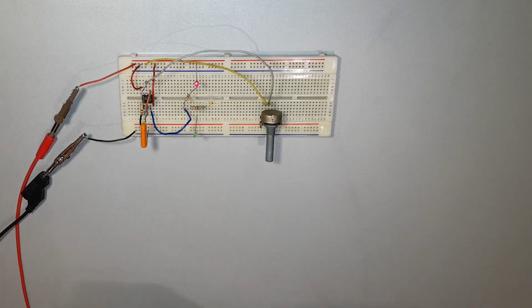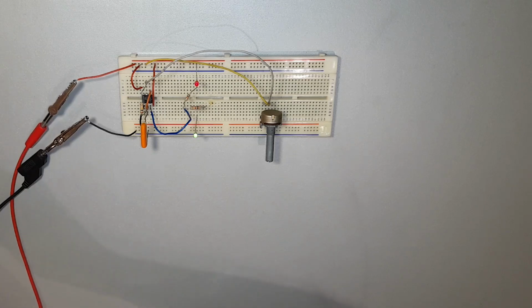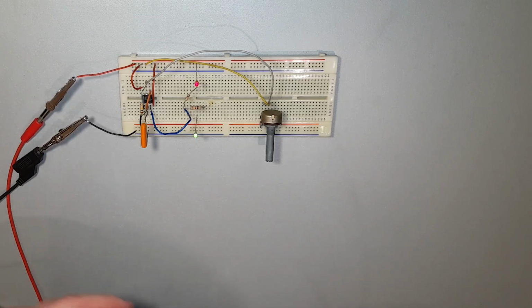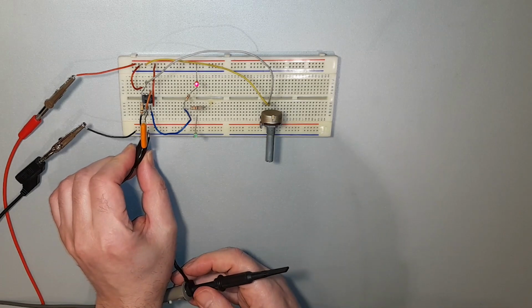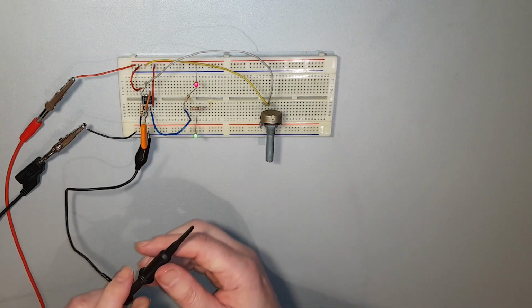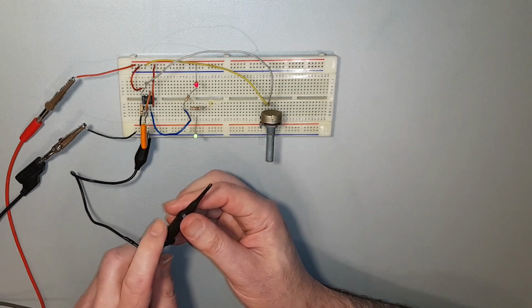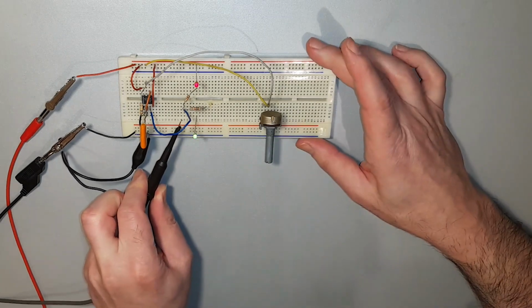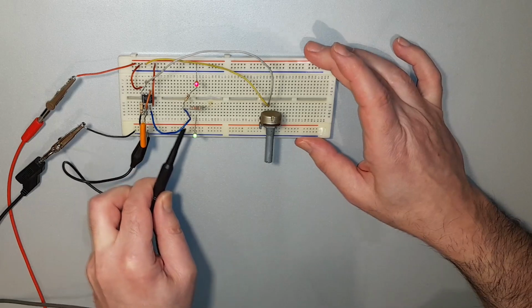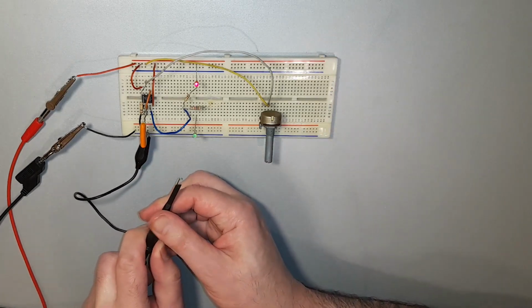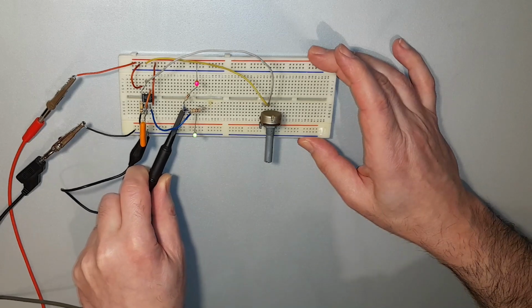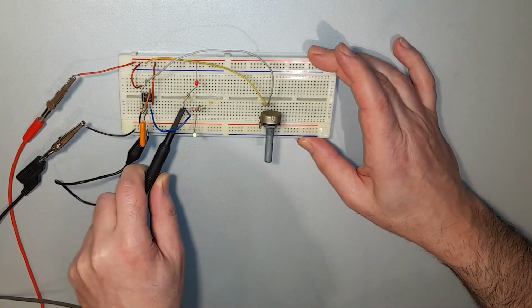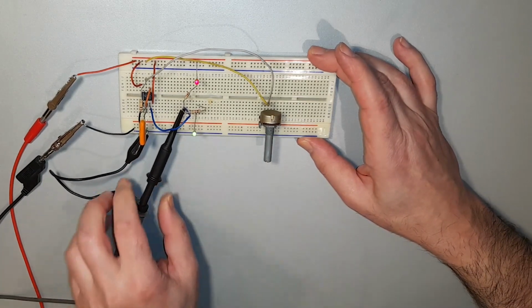So I'm going to plug in my oscilloscope. So negative to negative here. And then the output is on pin 3, which is the junction of these two little monitoring LEDs. So I'm just going to put that on this resistor point here. Can that clip on there? Yep, I think that's got a hold of that. That's great.